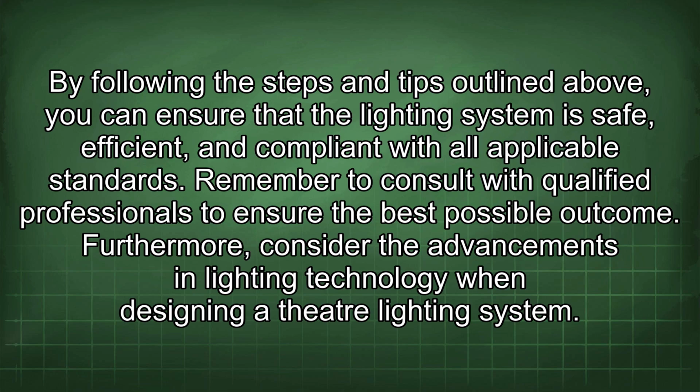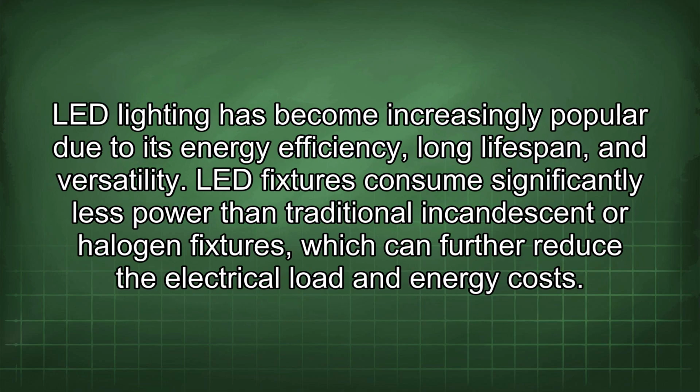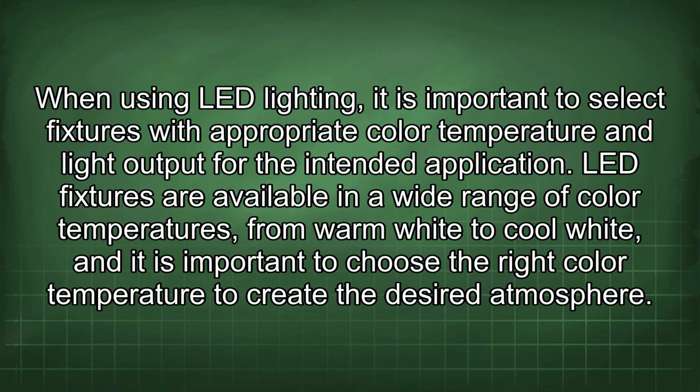Furthermore, consider the advancements in lighting technology when designing a theatre lighting system. LED lighting has become increasingly popular due to its energy efficiency, long lifespan, and versatility. LED fixtures consume significantly less power than traditional incandescent or halogen fixtures, which can further reduce the electrical load and energy costs. When using LED lighting, it is important to select fixtures with appropriate color temperature and light output for the intended application. LED fixtures are available in a wide range of color temperatures from warm white to cool white, and it is important to choose the right color temperature to create the desired atmosphere.